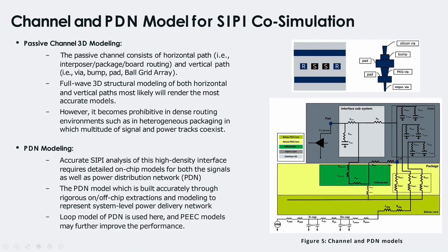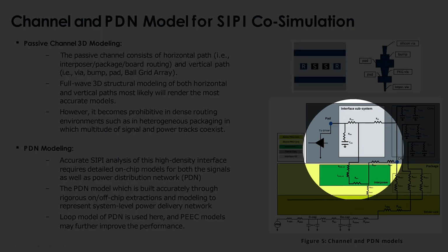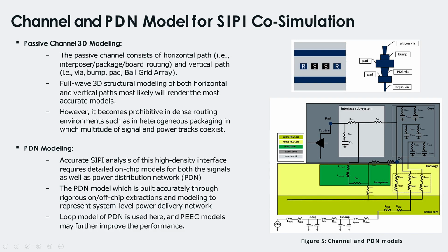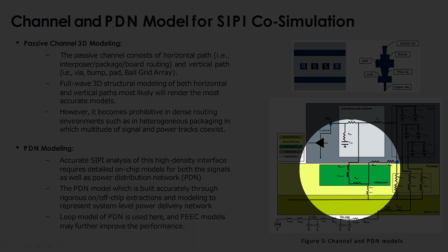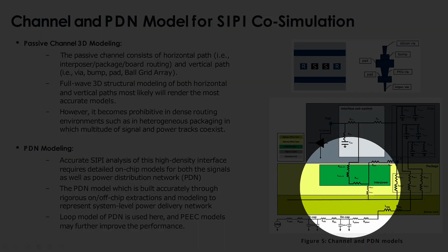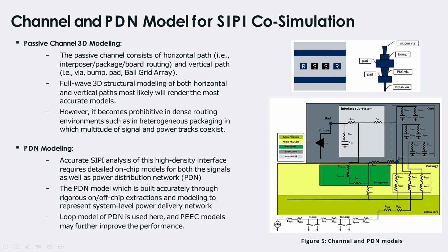And one thing if you're going to strategize this PDN is that this kind of analysis gives you the ability to do what-if analysis, meaning that eventually you're connecting this whole PDN to the pad of your transistor when you're using the transistor level models. So that gives you the ability to do what-if analysis. Let's say you're doing a design space exploration at the package level, so you should be able to sweep the parameters of the package in order to find out your worst case package.